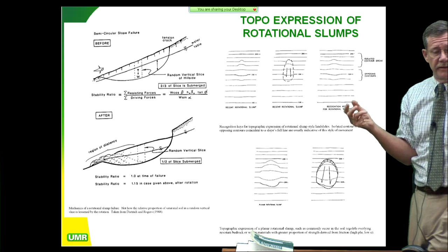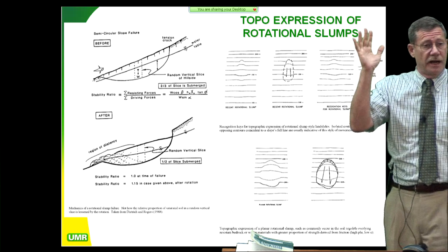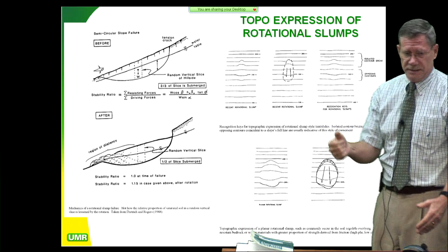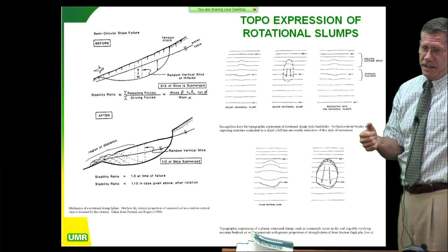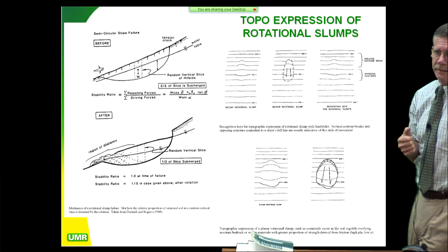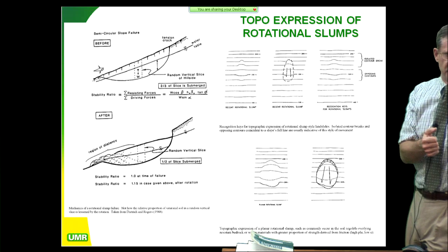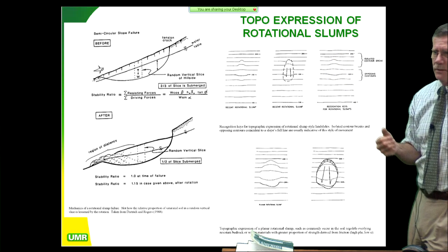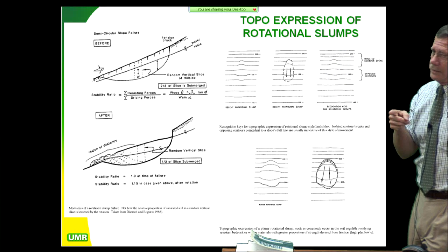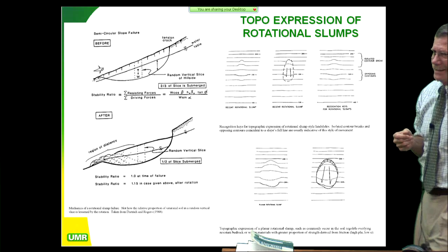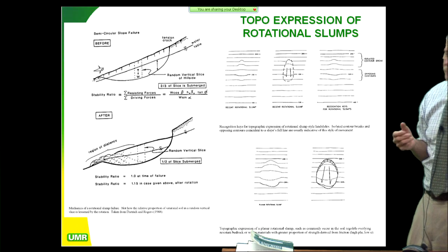In fact, if you're in an area that has very high trees or very high topographic relief and you're taking waypoints going down a channel, sometimes the USGS map will have a channel 40, 50, 60 feet away. It's not real accurate. So we have these old technology maps and this new technology way of locating ourselves. So the way to go is Google Earth. Take Google Earth with you and use that, and have your iPhone with you.